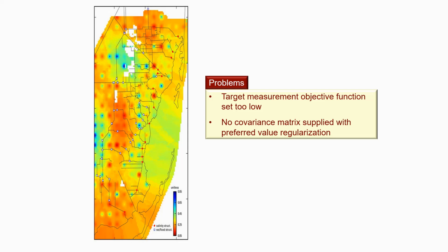If we don't use a covariance matrix, what we're effectively saying is that every pilot point can act independently of every other pilot point to get a locally good fit with a calibration data set. But that's often not what we want. If heterogeneity arises, it needs to be a little bit more spread out than that. So we end up with a parameter field that looks a lot better, that looks smoother, if we use a covariance matrix along with the preferred value prior information equations.